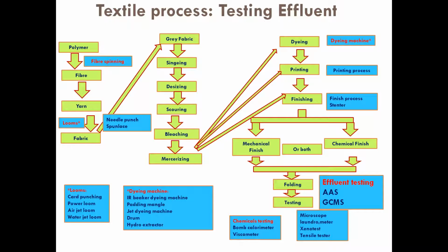There is a primary treatment where settling is done, and there is secondary where biological treatment is done, and then it may be a tertiary treatment where it may go through a carbon bed, or it may go for ozonation or chlorination. There are some tertiary treatments. So after that, your treated water is ready to be drained off in some receiving water. It may be river or riverlet, or it can be released to an open area.